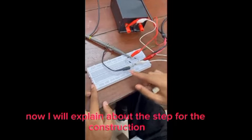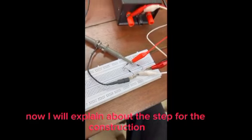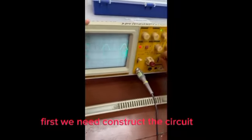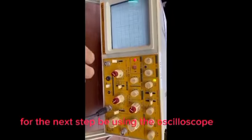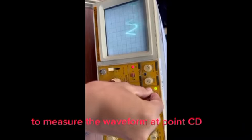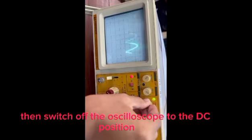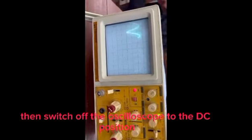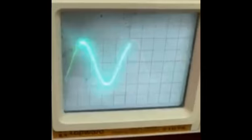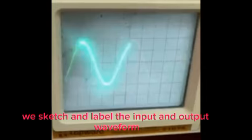Now I will explain the steps for the construction. First, we need to construct the circuit. For the next step, we use the oscilloscope to measure the waveform at points CD. Then, switch the oscilloscope to the DC position. Finally, we sketch the input and output waveform and label it fully.